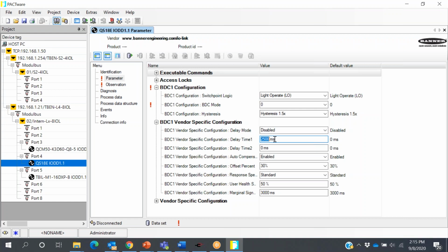We don't just have these bricks for field locations. This is a USB single IO link master, so I can just connect one device to it through the M12 connection, USB this to my laptop, and do some configuration for my sensor. So putting your toe into the water, you can just do something as simple as that.